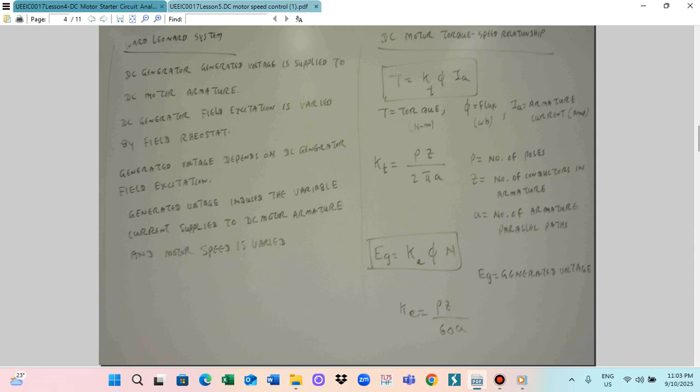This is the equation to calculate the motor torque: T is equal to KT phi Vt divided by Ra, minus KE KT phi squared divided by Ra. In this case, KT and KE are already given. Vt is the terminal voltage, Ra is the armature resistance.